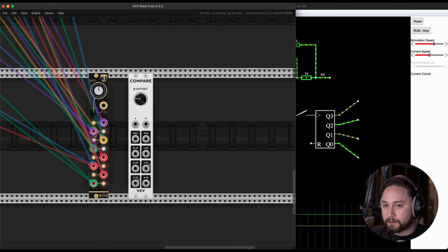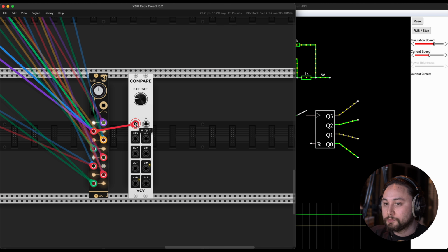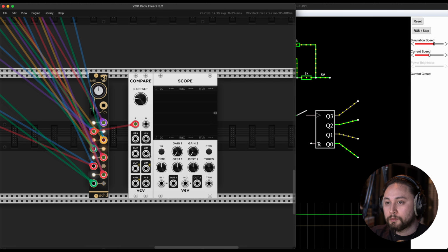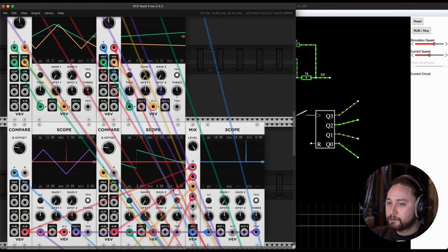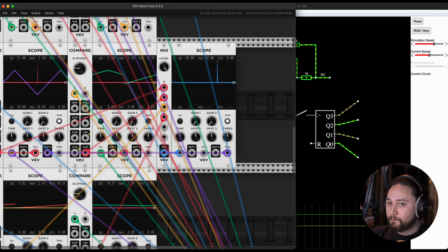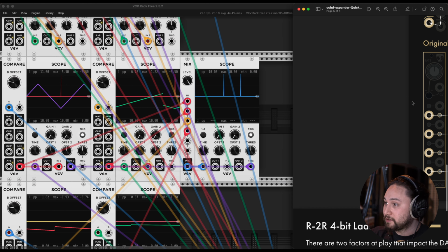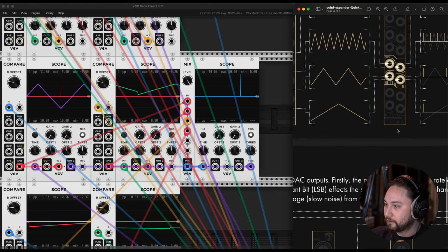So let's look at this LFO, for example. Anytime it's over, it's going to be giving me a high signal. Anytime it's under, it'll be a low signal. Center that offset. Here we go. So 50-50 duty cycle square wave. Again, similar to this trigger extraction, we managed to align a replication of the phase that exists naturally here.